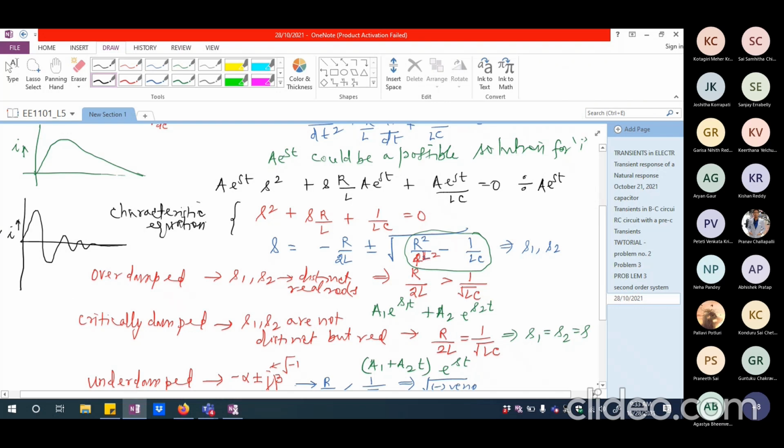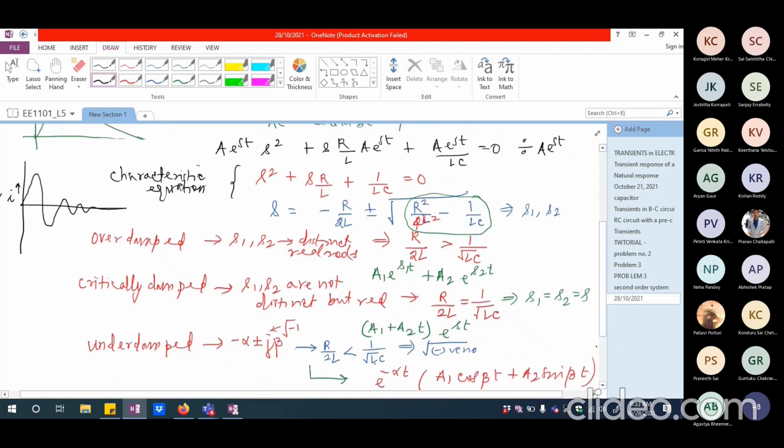So in this particular case, very clearly, if the resistance is quite high, then this in all probability will not be possible. When the resistance is larger, in all probability it will show an overdamped response. But when it is transitioning from overdamped to underdamped or vice versa, it might just go through the critically damped point. So this is the crux of what we discussed yesterday.